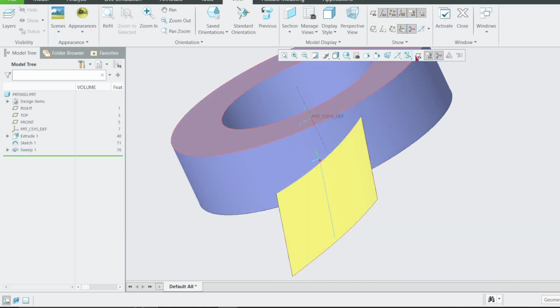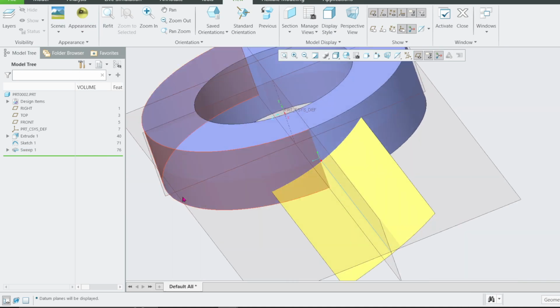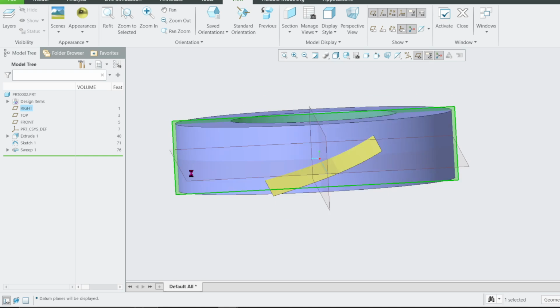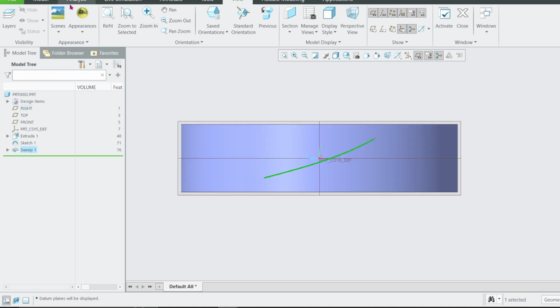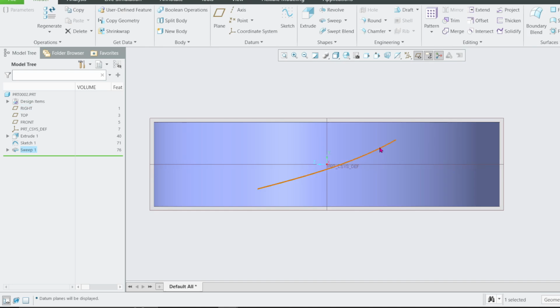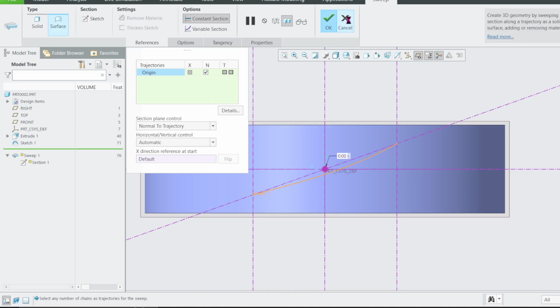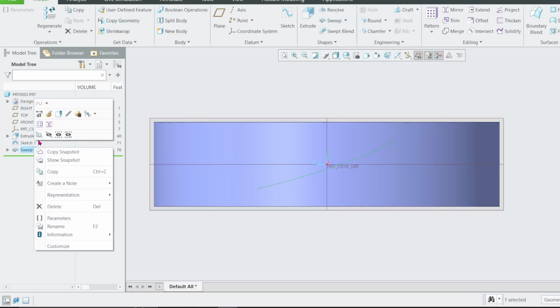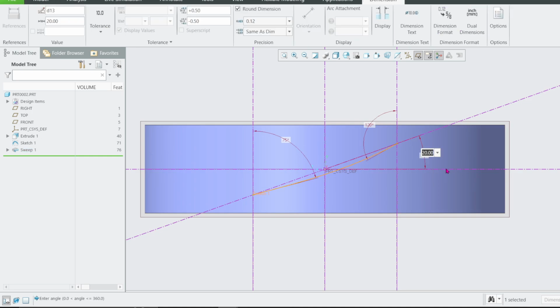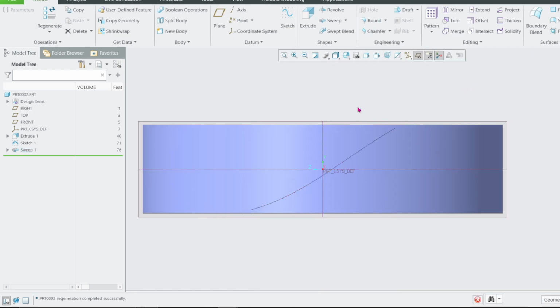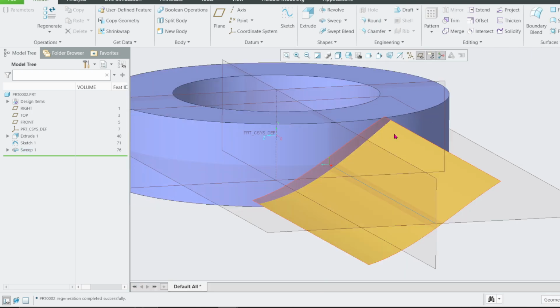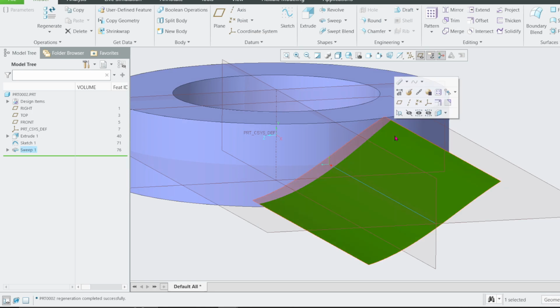You see my surface? If I view from this side here, like that, it has a uniform cross section. You can see. But remember the one we saw, it was twisting. And I said, for us to be able to twist this cross section here, the angle we need to change. Let me use D instead. This is a value you need to change. If I change this from 20 maybe to 30, see now, it is rotating all the surface.